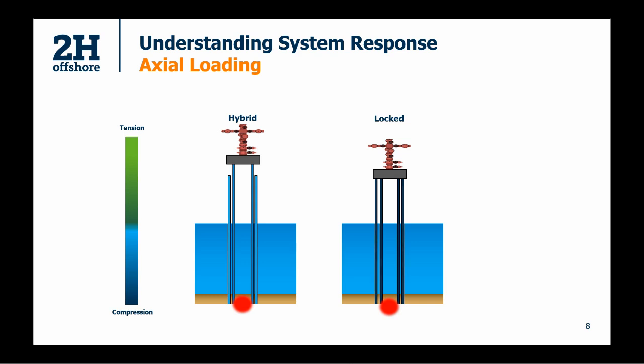So what happens is that, again, the loads transfer until you reach an equilibrium in the wellhead. But because the conductor has been essentially pulling back on the wellhead to hold it in place, you'll notice that you see less movement in the wellhead. But it also means that because the conductor was attached to the wellhead, as the casing tries to push up, it's pulling on the conductor.